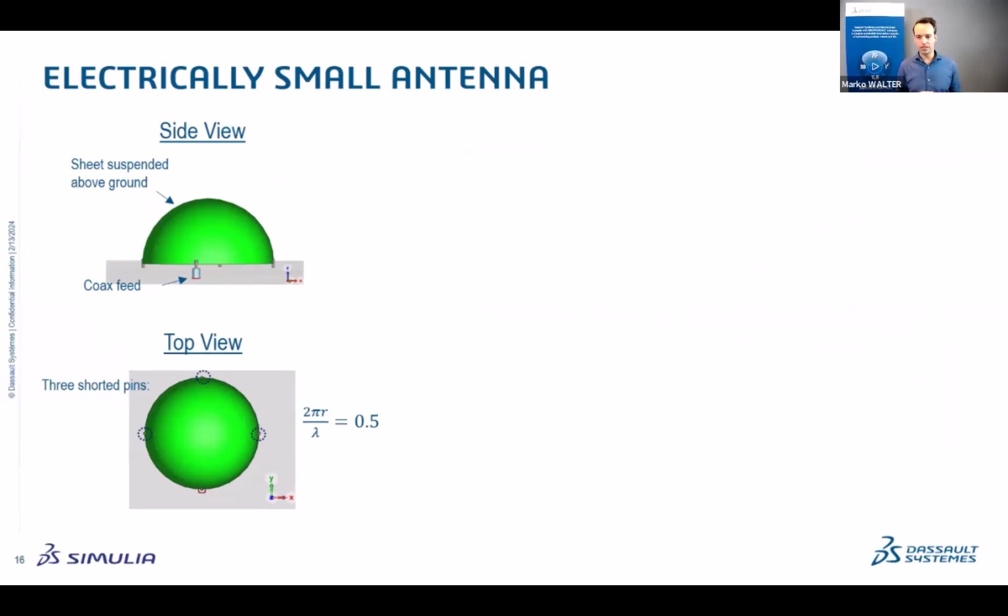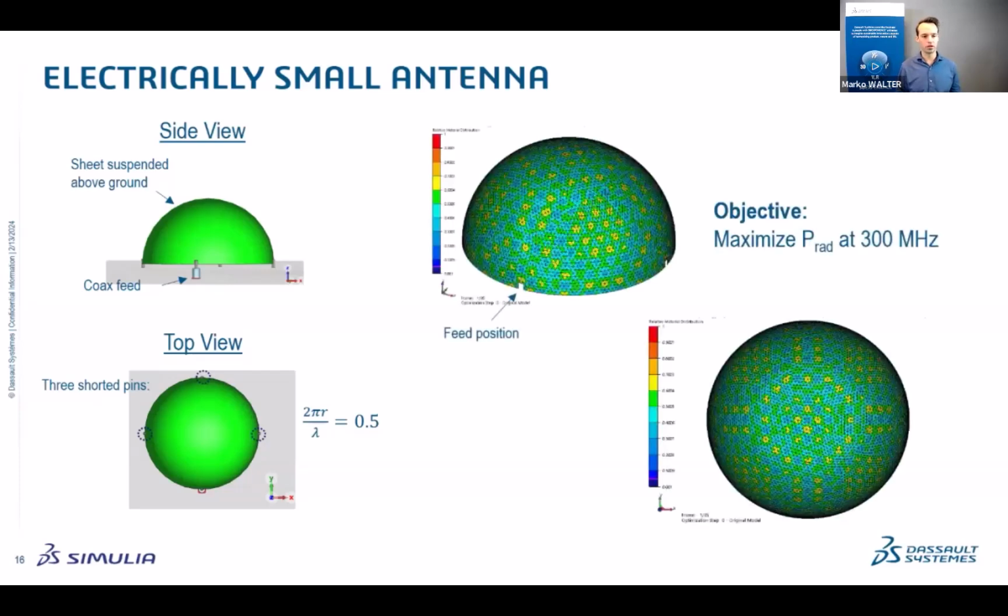And these pins are basically just, again, seeding the design space to run in a certain direction, or to try and get a good topology in the end. So not being completely black box. And then in addition, we also use a type of perturbation density distribution. So we don't start from a uniform density distribution, but actually it's sort of perturbed, as you'll see when I show you this picture there.